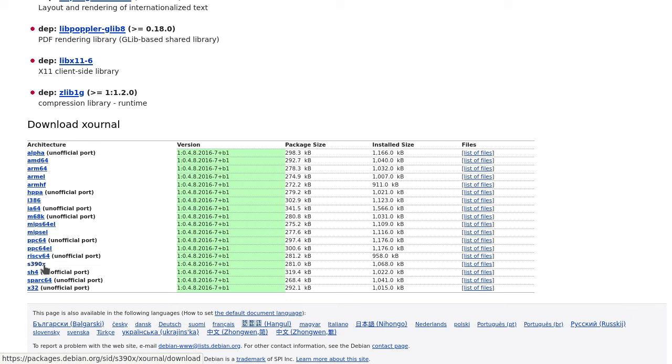We're talking about the US, so the voltage is about 100. We'll just call it 100, so it's easy to calculate. So the current needed is the power in watts divided by the voltage, which is 100. So you've got 4,000 divided by 100, which is 40. So that means your LAN party needs 40 amps. Okay? So you go to the circuit breaker.